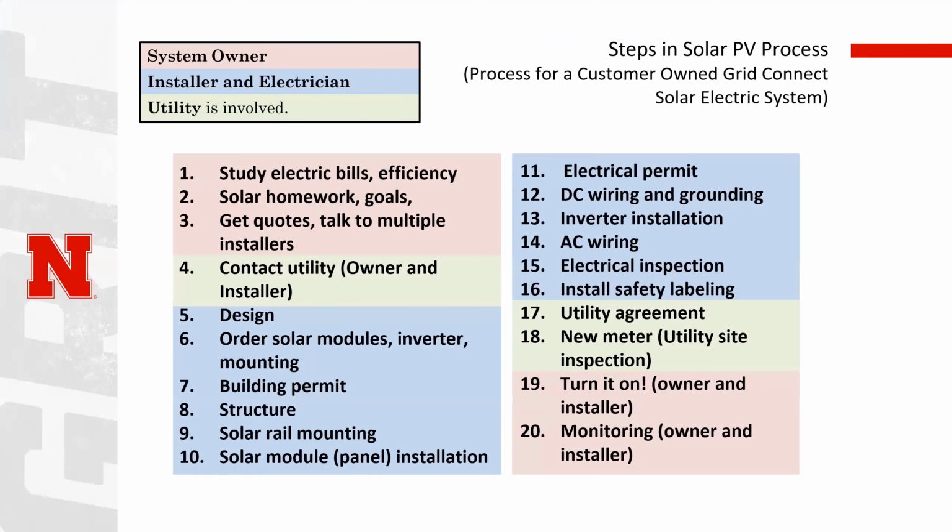But beyond showing off, there are some inverters that require it being hooked to the internet to activate the warranty. Wow, monitoring is really, really important if it activates a warranty. And so in all cases, we should be monitoring those online if at all possible. And so that can be forgotten about. Some installers don't do that as well as others. So you want to get that monitoring hooked up.